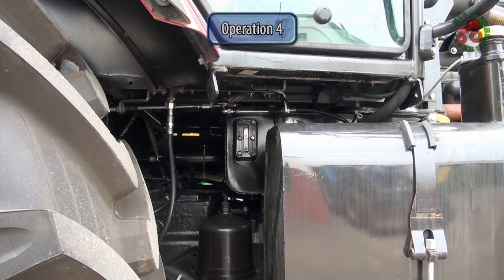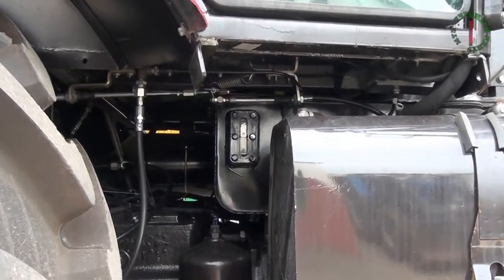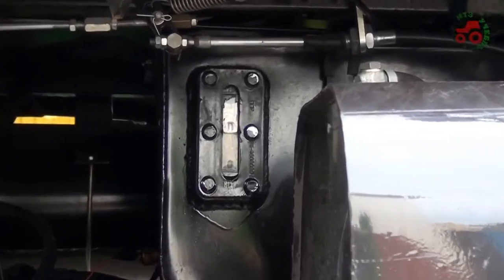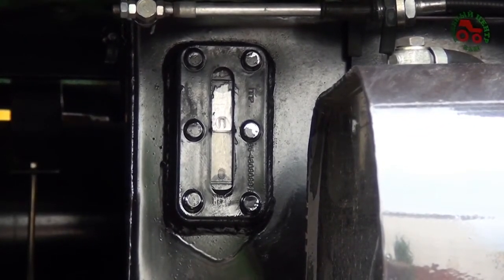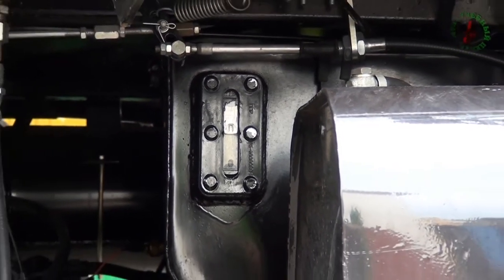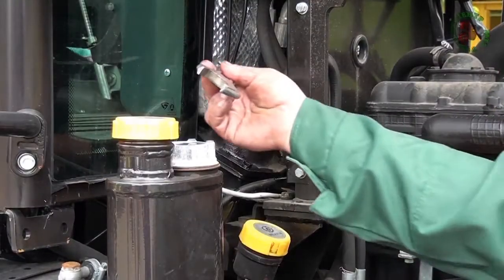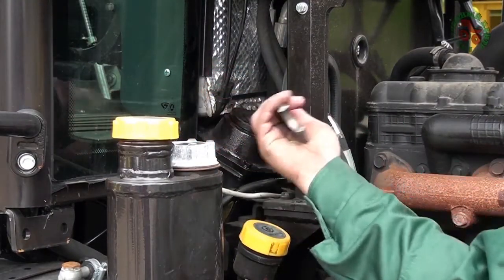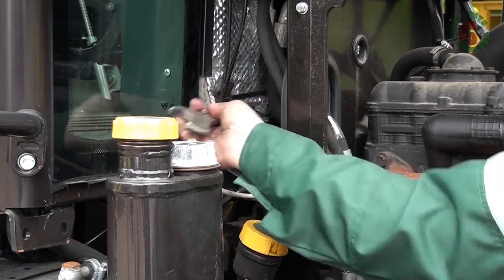Operation 4. Check oil level in the hydraulic steering control tank. Check the oil level according to the oil level gauge in the hydraulic steering control tank, located on the right side of the clutch case. The oil level shall be between marks O and P. If necessary, remove the cap with the valve and add oil up to the mark P.